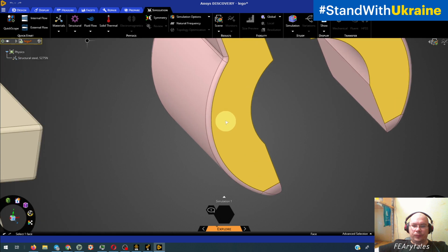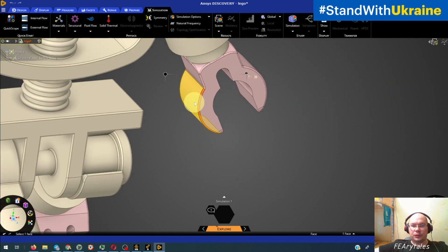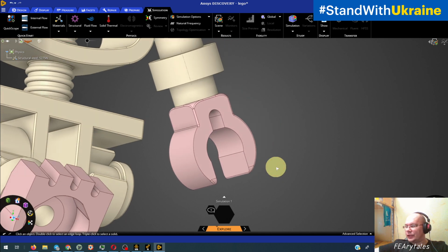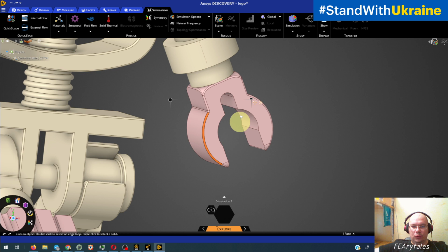First of all, we select this fillet, this round, and we can delete it. But it's very tricky to delete all these objects one by one. So in SpaceClaim and in Discovery there are processes to simplify this with power selection.